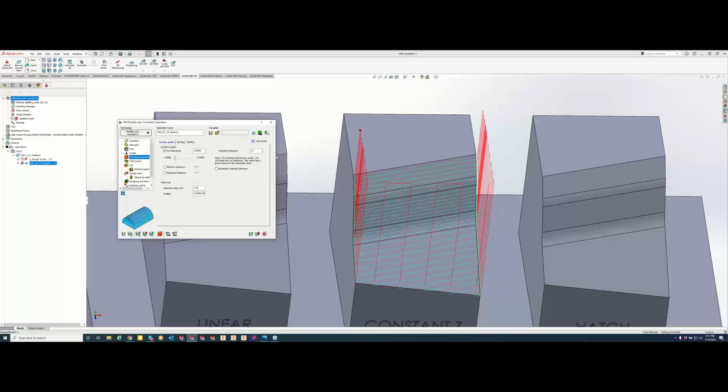Okay. Chaining tolerance, something that we really don't have to mess with a lot. Like I said, our default is definitely good right here, but maybe as we're going over a curvature surface, we're not hitting all the areas, especially in a smaller area. So we can turn down our chaining tolerance right there. You can see it's just adding more points in there for you guys.